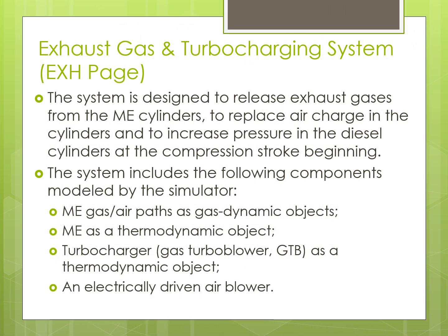Exhaust gas and turbocharging system. The system is designed to release exhaust gases from the ME cylinders, to replace air charge in the cylinders and to increase pressure in the diesel cylinders at the compression stroke beginning.